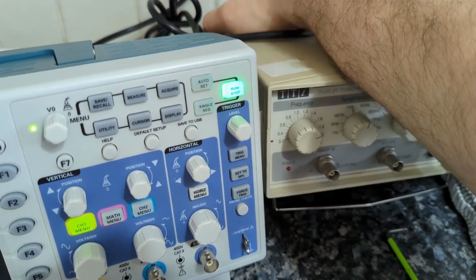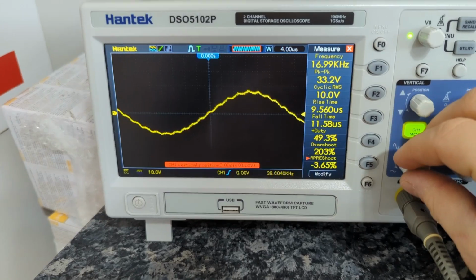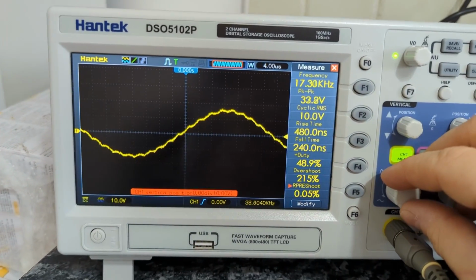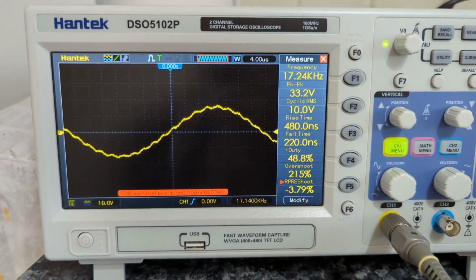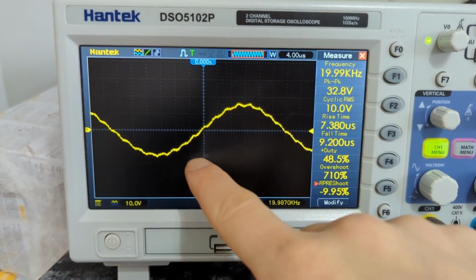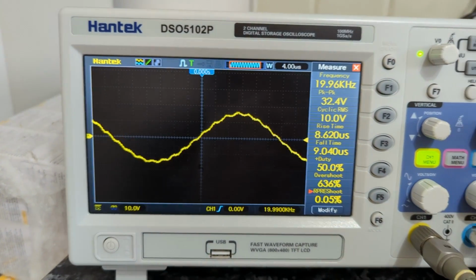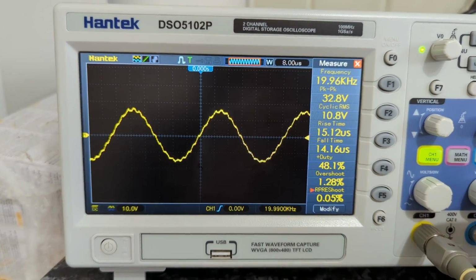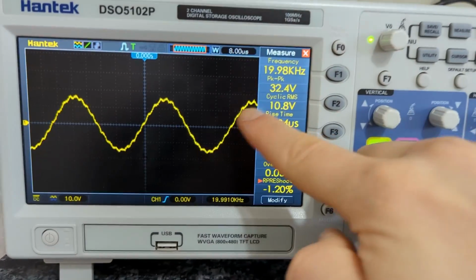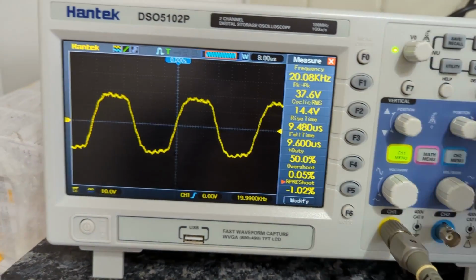And this is the thing. Then if I connect my generator, so this is a sine wave playing, and you can see that there is a 17 kilohertz light. Let's do a 20 kilohertz sine wave, but on top of it, it's that 300 kilohertz wave that is modulating. And for this reason, if I'm going to switch it, we're going to keep it at 10 RMS. If I'm going to switch it to square wave, you can see this.